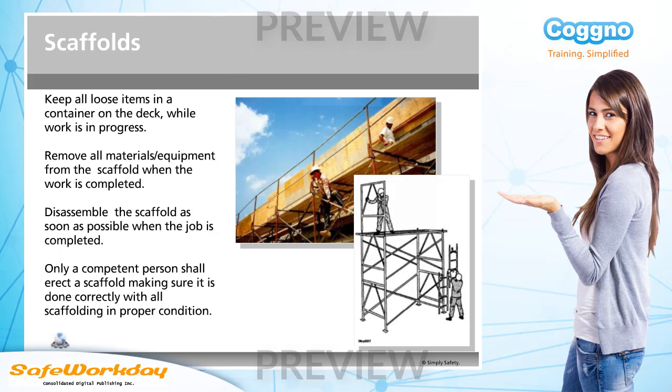Keep all loose items in a container on the deck while work is in progress. Remove all materials and equipment from the scaffold when the work is completed. Disassemble the scaffold as soon as possible when the job is completed. Only a competent person shall erect a scaffold, making sure it is done correctly with all scaffolding in proper condition.